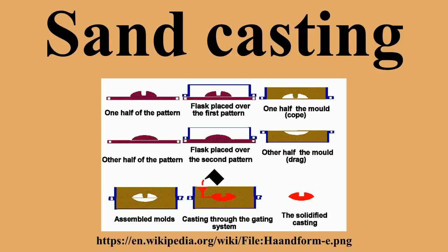Tools. In addition to patterns, the sand molder could also use tools to create the holes. Molding box and materials. A multi-part molding box is prepared to receive the pattern. Molding boxes are made in segments that may be latched to each other and to end closures. For a simple object, flat on one side, the lower portion of the box, closed at the bottom, will be filled with a molding sand.